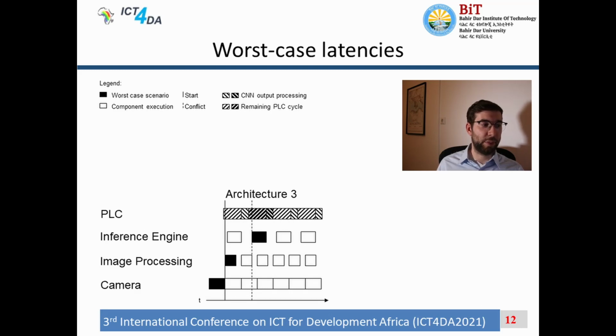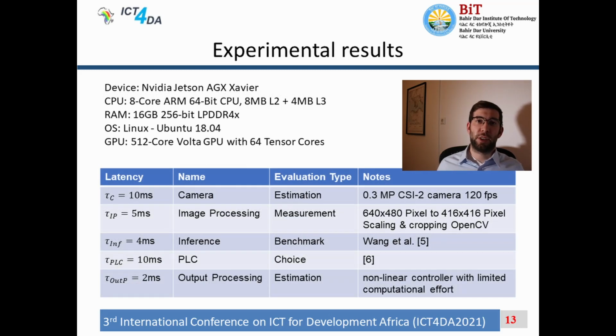Then we can only miss one image preprocessing cycle and one of those post-processing cycles on the PLC, which is shown as the remaining PLC cycle in the legend. For those architectures, we conducted an experiment whose results are shown in the table below. We used the previously mentioned NVIDIA Jetson AGX Xavier board in the development version, which has the specs shown.